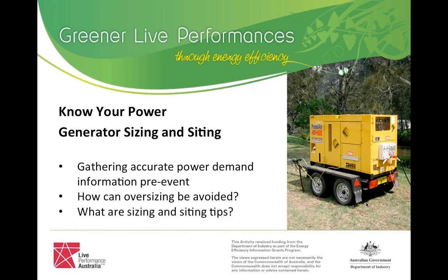We will hear hopefully from some generator techs coming up, to talk about the effects on fuel consumption when you have a smaller number of larger generators that perhaps aren't being utilized all of the time, because we see the reverse of that happening in some scenarios where the most efficient option is actually to have more, smaller generators, so that it enables you to power them completely down when they're not needed.